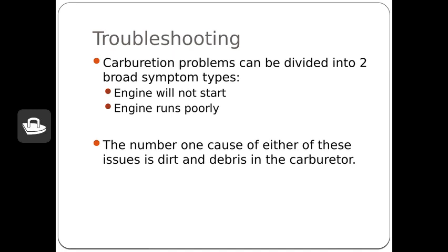Sometimes it's going to take a little bit more effort, and we're going to have to actually clean the jets out. That could entail utilizing carburetor cleaner. That could utilize parts cleaner, and we have to soak it for 24, 48 hours.